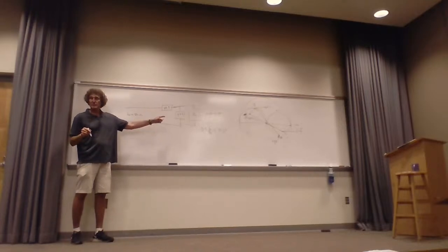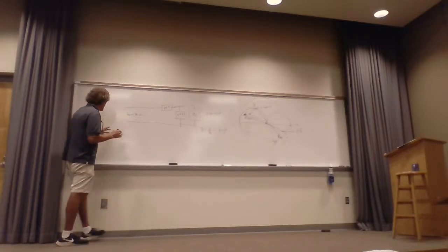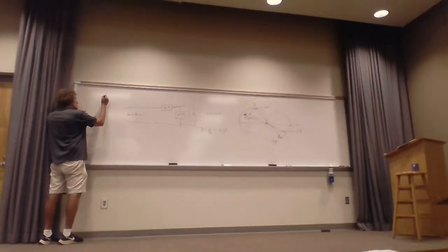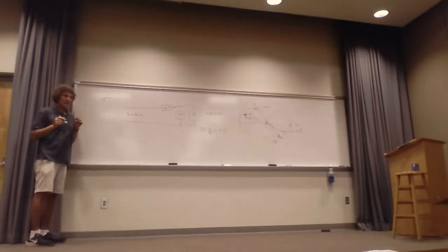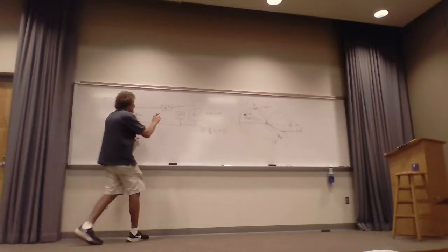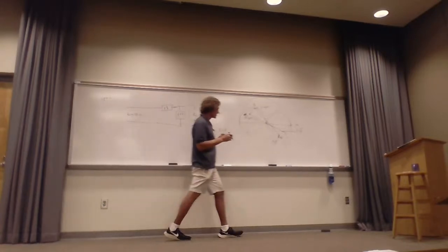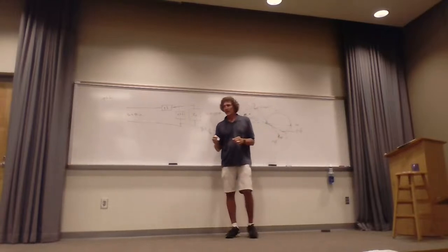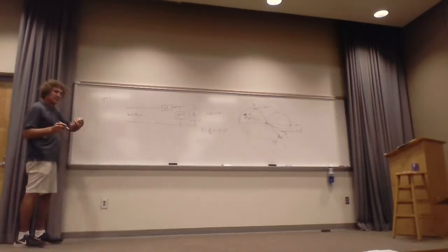So let me show you how this normalization works. First, I'm going to talk about the j3. You see, that's an impedance, right? It's in series, correct, class? Well, think about it. For an inductor, in general, an inductor has an impedance of j omega L, right? 0.3 or 3? It's 3. I put 0.3, I'm so sorry. This should be j3. My bad. So that's the impedance, right?